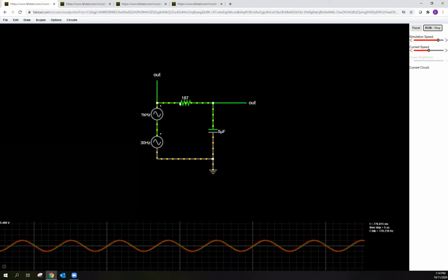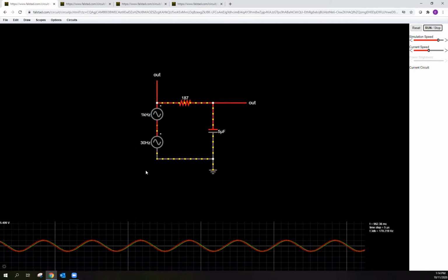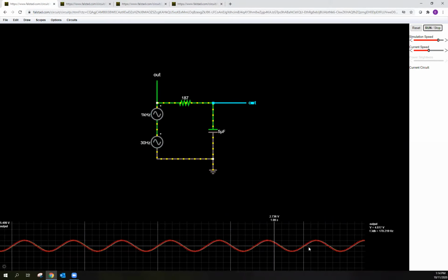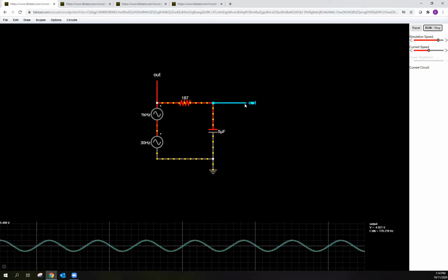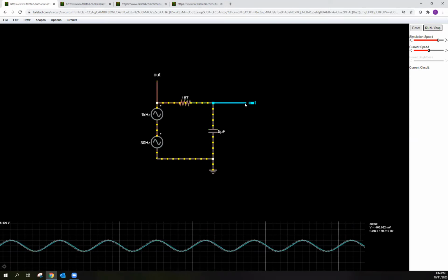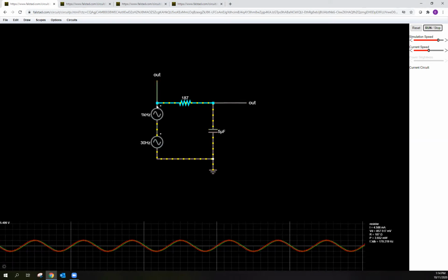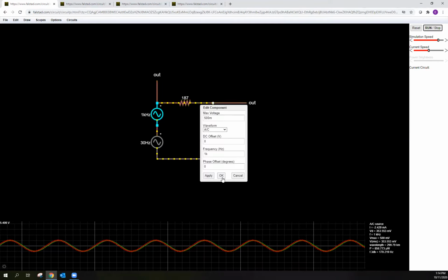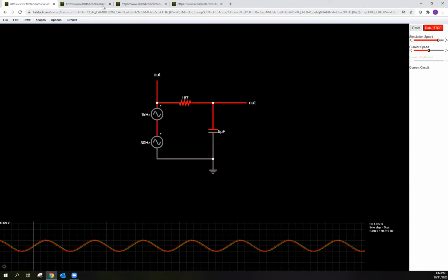And I hope what you can see is I'm measuring two outputs. This measurement is actually the input. Think of this as the Vi. That is the red line here, okay? And the output here is the green line. Notice the green line is smoother. It's been low pass filtered. It filters out all the nasty high frequency content from this signal, okay? All right, so let me pause this.